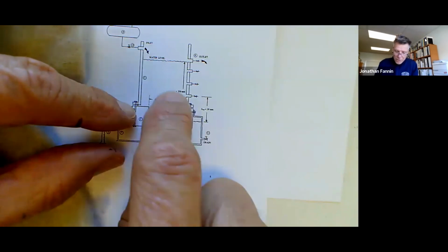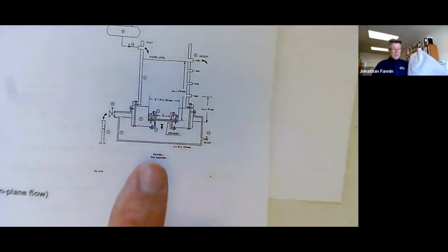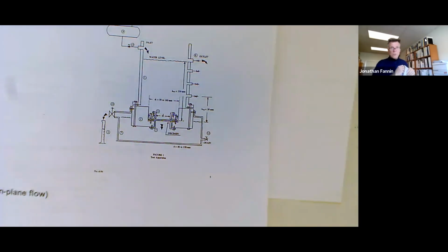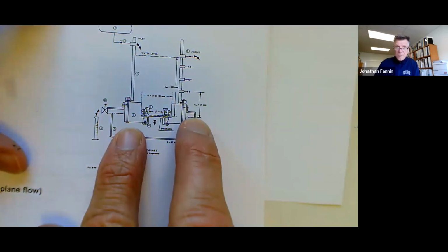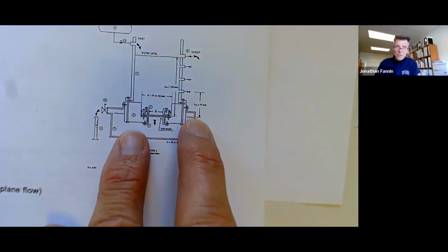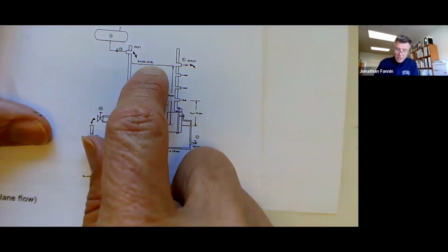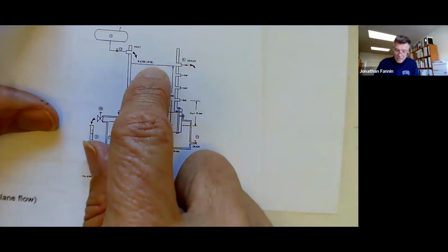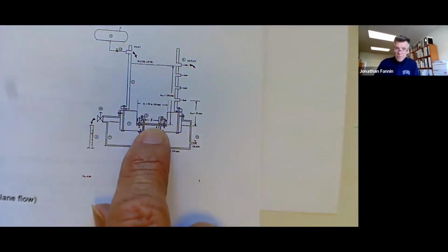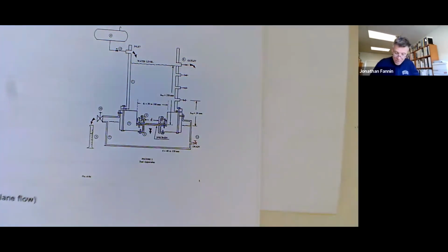And then we're going to conduct a constant head flow test, just like we would do to get the permeability of a soil. We put the soil in a rigid wall permeameter. We've got to be a little clever about getting it fully saturated and so on. And then we can carry out a constant head or a falling head permeability test. We do a constant head permeability test on the geotextile specimen. It's just going to be down in here.